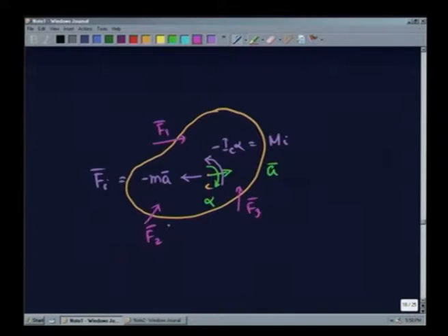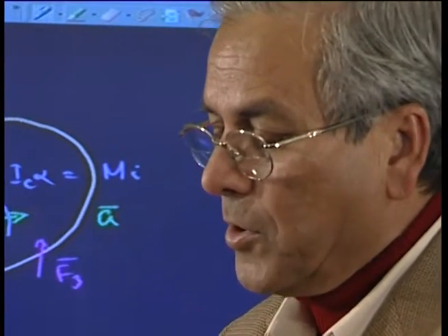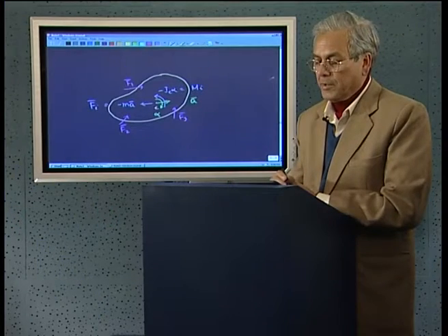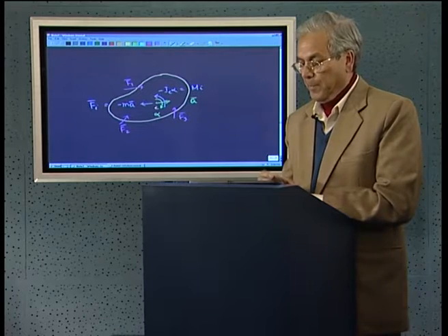this system will be in static equilibrium, because the resultant effect of this force and this moment is nothing but producing a force which is equal and opposite to the resultant force produced by this. That means they will nullify each other and this system will be in static equilibrium. So, this is the technique which we will use, D'Alembert's principle: we will add the inertia force of each and every member to it, and then treat the whole system as in static equilibrium.